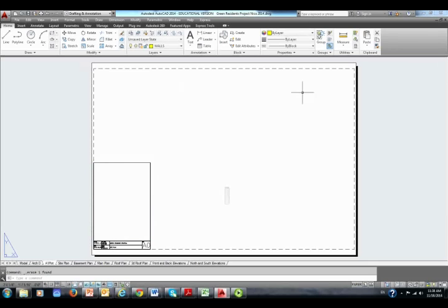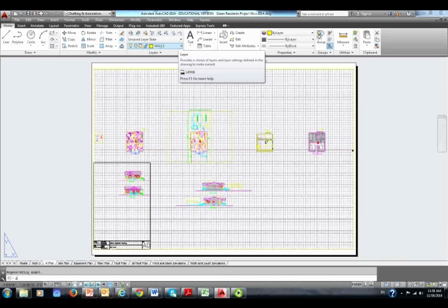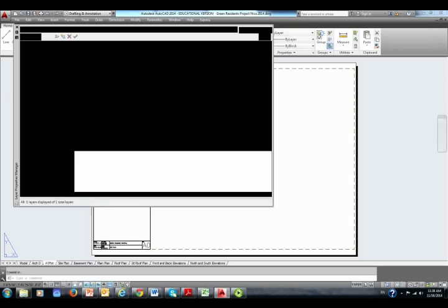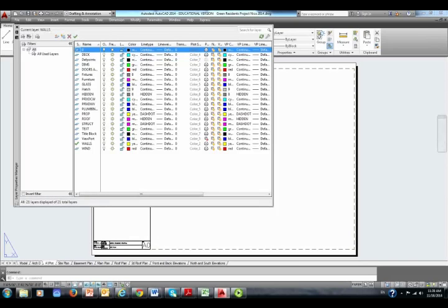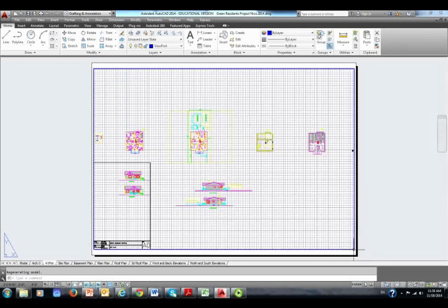For the purpose of having pickable corners, I'm going to make a new view, and I'm going to simply hit enter. Once we pick enter, and by the way, I created it in wall, so let's undo. Let's do it right. Let's go to layers and see if Nico has a viewport layer. Viewport, he is all organized. So I'm going to make that viewport layer current, close it, and in this I'm going to type MVIEW, enter, enter, which creates a viewport in maximum printable space. I do not want to worry about my grid display.